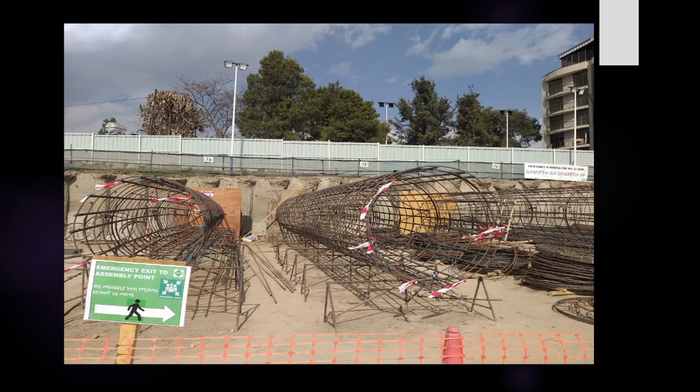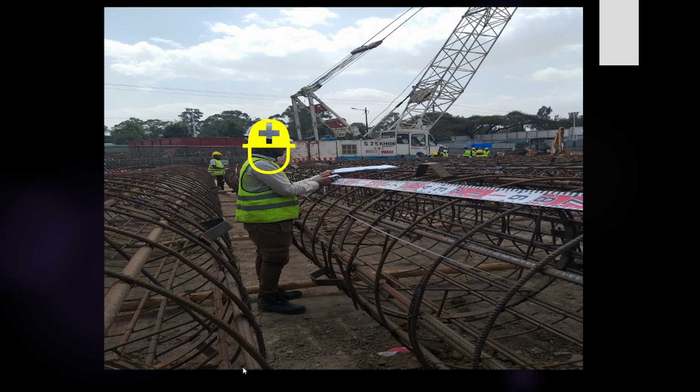So here it is. This is how it looks. This is a maximum of 12 meters, and then based on the length of the pile, it can be overlapped when it is inserted into the pile. Before we insert our reinforcement, we should check the length, the width, the diameter of the pile, the center to center of our stirrups, and the total length of our pile.